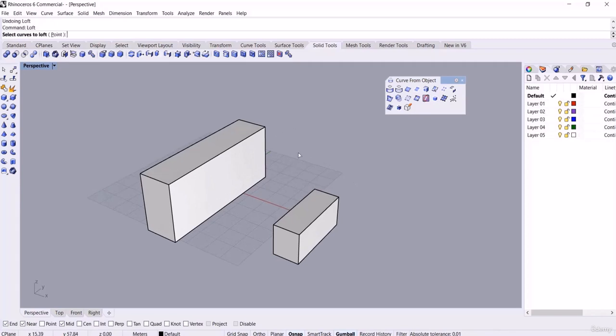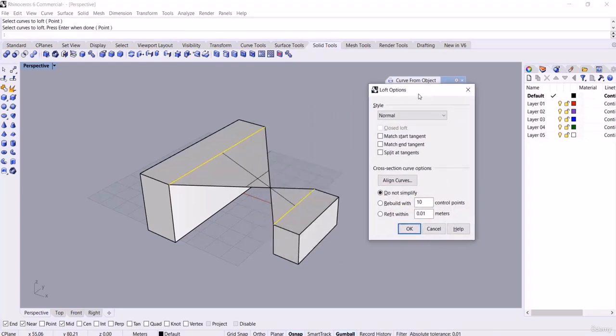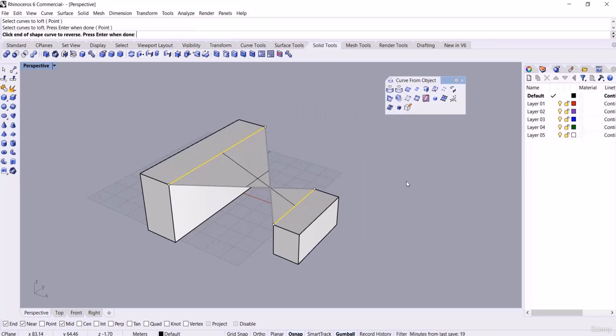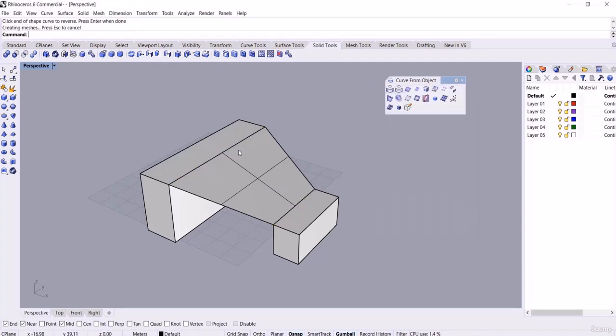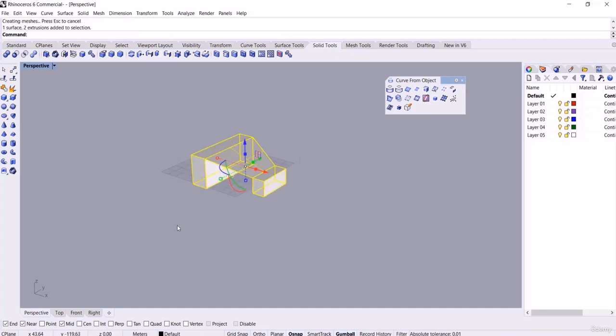And even for aligning the curves after creating a surface by loft, here if I specify two ends of the two curves or surface edges which are not aligned with each other, then we will have such a result that if we want to fix it, we should align the curves. Check this out. I mean, here we are aligning the curves, but we operate on the surface edges, not the curves. So this was an example in working with the loft command. In the continuation, I'm gonna exemplify another case by using the sweep command.